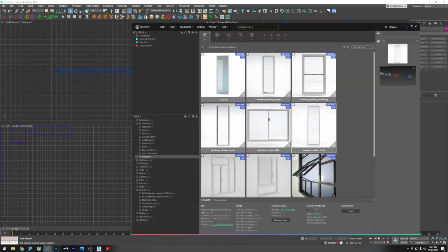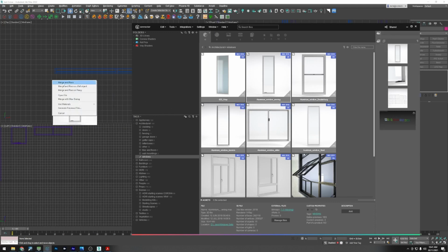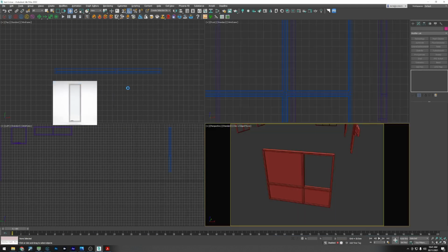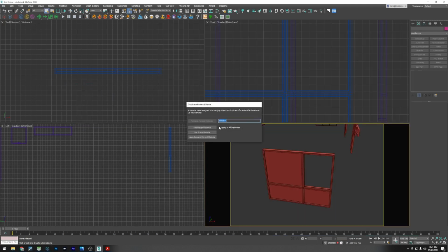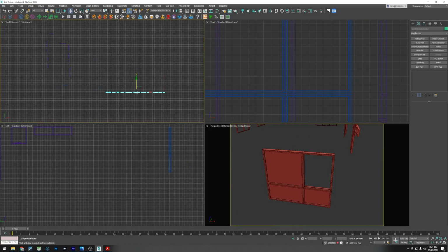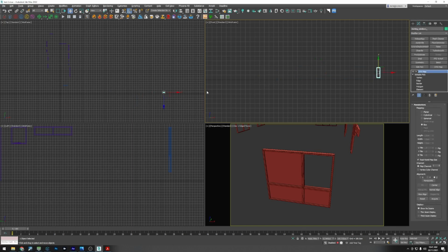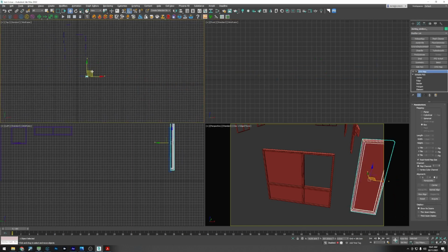We're going to go to connector again and bring in an aluminium awning window. Again, these come in with a whole bunch of different options, different sizes and shapes, different panels, amounts. So you can see there, we just need the single one. Delete all the rest. Drag this over to our window.